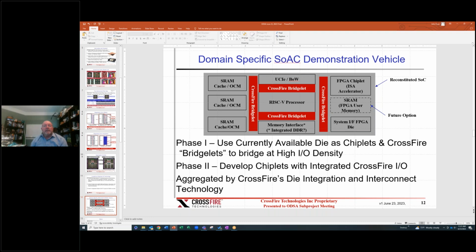So we think we can, in our application programmable array, enable a customer to go through and tune their design and figure out just how much memory they need, and then build something that, pulling from a chiplet RAM catalog, can get very close to their requirements. So it's optimized. In some cases it may not be worth that, but in others everything's going to count, and we want to be able to support it. The RISC-V processor, there are several examples out there, so we would probably want to use one of those.